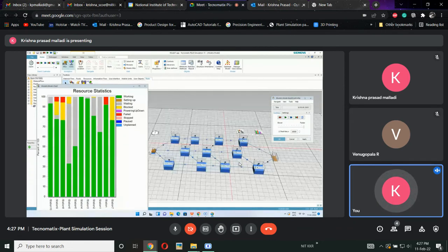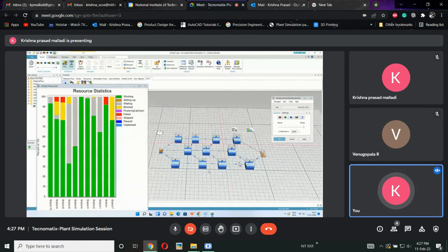So this is how we are going to run the simulation. If we consider this as a simulation, every machine will have one failure, so every machine will have failure, blockage, waiting, and green. There are two things mandatory. Failure is mandatory, we can't change the failure. At the same time, we can't change the green also. So we need to reduce this yellow phase. That is exactly our role as a plant simulation expert using this software. Somehow, by using conveyors, or by increasing the length of the conveyor, or by placing alternative machines or using some other process, we are going to reduce this blockage. That is exactly what we are going to do in the optimization part.